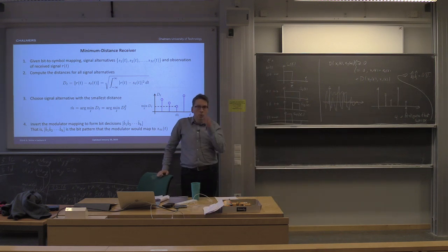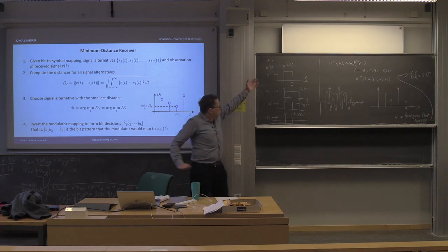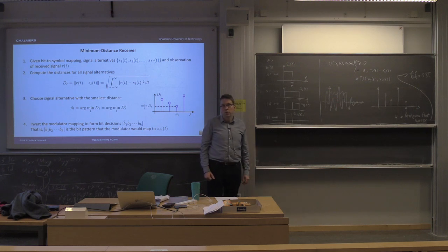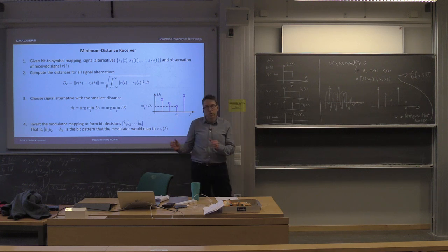Okay. So, are there any questions on the receiver now? This minimum distance receiver, its functionality. Actually it's a fairly simple device. We just take the received signal, we subtract off all the possibilities and figure out what the distance is to all the possibilities, and then we guess that the one which is closest to what we've seen is our guess. Minimum distance receiver.